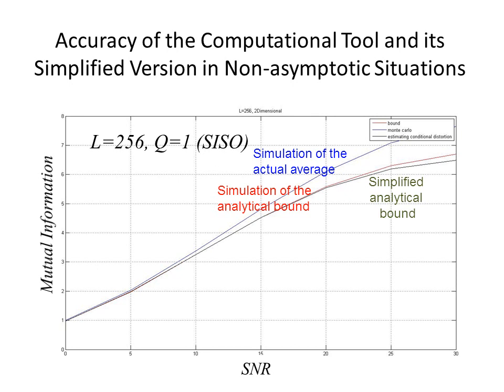I have modeled this as an additive noise. And in the paper, you will see some expressions for this essentially quantization noise. A good part of the derivation is based on an actual lower bound, and then at some point there are approximations, but the approximation serves our purpose of showing that the capacity approaches the capacity of AWGN.